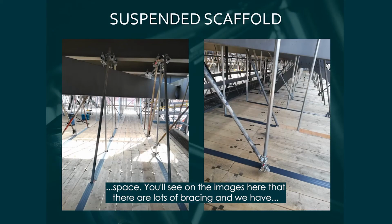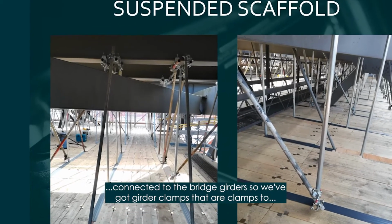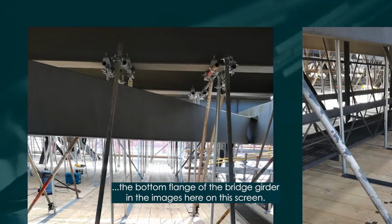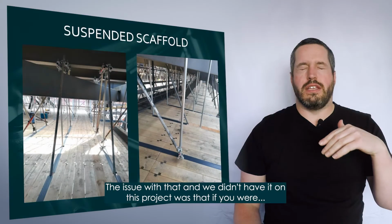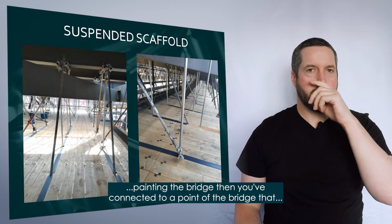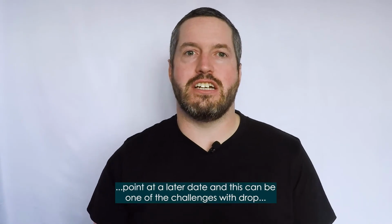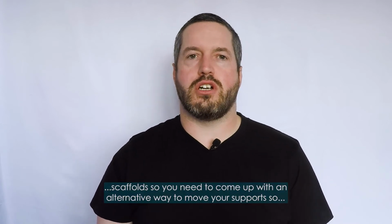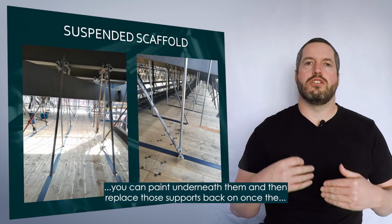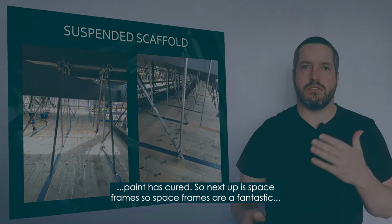You'll see on the images here that there are lots of bracing, and we have connected to the bridge girders. So we've got girder clamps that are clamped to the bottom flange of the bridge girder in the images here on this screen. The issue with that, and we didn't have it on this project, was that if you are painting the bridge, then you've connected to a point of the bridge that you need to paint. So you will have to move that connection point at a later date. And this can be one of the challenges with drop scaffolds. So you need to come up with an alternative way to move your supports so you can paint underneath them and then replace those supports back on once the paint has cured.